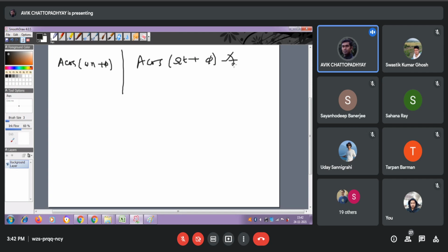So this kind of symbol people use. After this, what we got, if you were present in my first two classes, you know very well how to represent it. A cos, just after sampling, the argument after cos, I'm writing here: capital omega, then instead of t, it should become n into capital T. And you know what that capital T is? Capital T is basically the sampling interval or sampling period.